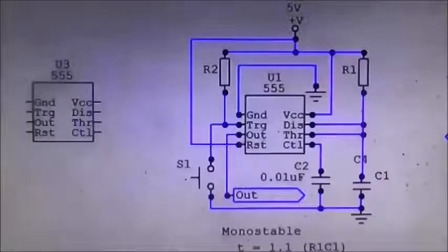And of course, if the output driver is high, we're getting 200 milliamps of current through there. And we can drive a small LED or something like that, as we saw in the practical circuit on breadboard. If we want to drive anything bigger, it can drive a transistor very, very easily, and we attach that to the output and let the load of the transistor be the object driven.